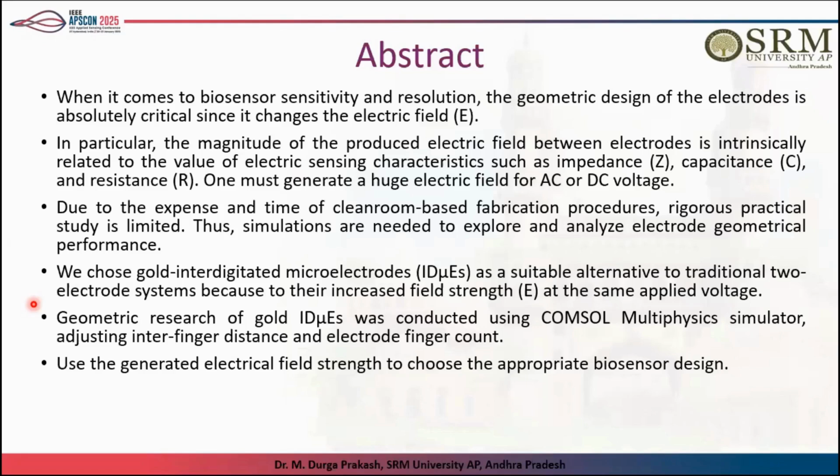All this work was carried out using interdigitated microelectrodes in the COMSOL Multiphysics simulation software, adjusting the interdigitated electrode interfringe distance and the electrode fringe count. All these parameters were taken into this work. We observed the generated electric field strength to arrive at an appropriate biosensor design. This is the brief abstract of this work.